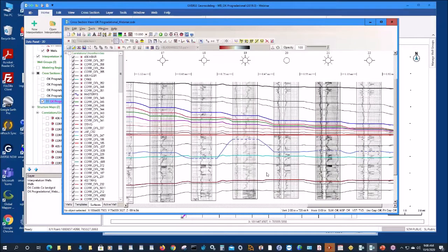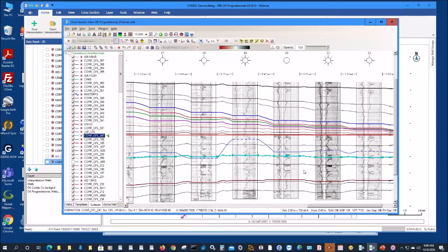So I've got a really well-controlled surface down here, this OFL 247 surface. I can go into my Geosurface Model Properties dialog and set up conformance, using my well-controlled 247 surface to constrain this poorly controlled CS2 surface that I've picked. Let me do that as a quick demo.